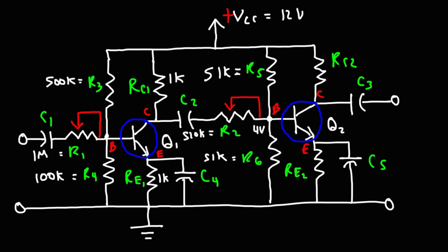During the second stage of the transistor, you want to make sure that the current gain is relatively high. The first stage is useful for increasing the voltage gain, but the second stage, you want it to increase the voltage gain if needed, but also the current as well. And so to increase the current gain, you want to decrease the value of RC2.